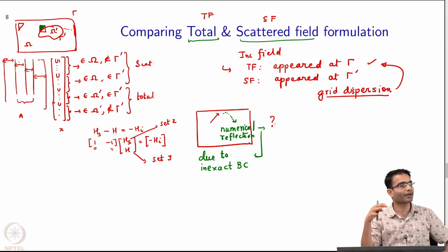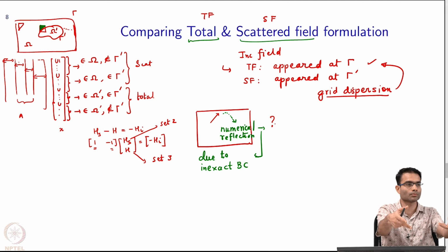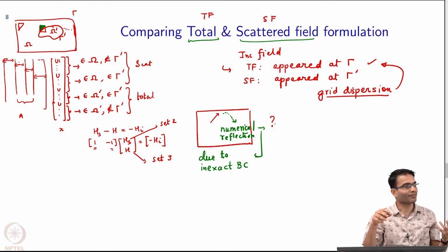All microwave and radar studies, if you go to their labs, they have these anechoic chambers where, if you want to characterize an antenna, you don't want some spurious reflection from the wall. Supposing I do a measurement in this room, I am trying to measure the radiation pattern of an antenna, but without realizing something has hit the roof and come back and my measurement is corrupted by these reflections. I want to cut it out. So, what do I do?